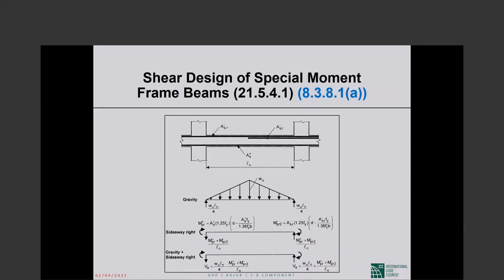Okay, the gravity sitting on the beam would be 1.2 dead plus 0.5 live. It is not 1.6 dead, it is not the gravity combination, it's the gravity part of the seismic additive seismic load combination. That's kind of important. So this gravity is 1.2 dead plus 0.5 live.